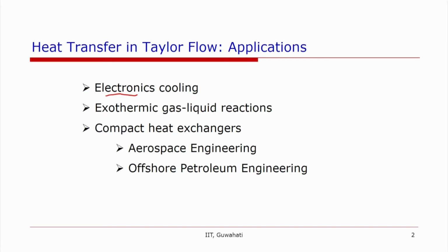That increases the requirement for the cooling of the electronic equipment, because when the number of chips increases, a larger heat flux needs to be removed. So at one stage the number of chips that can be put is limited by the heat flux that can be removed from the surface.